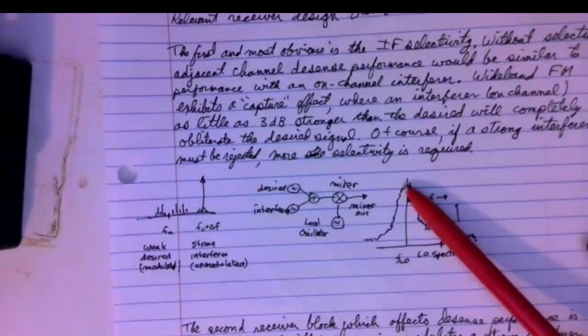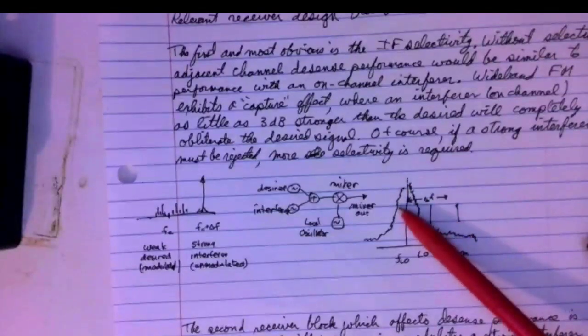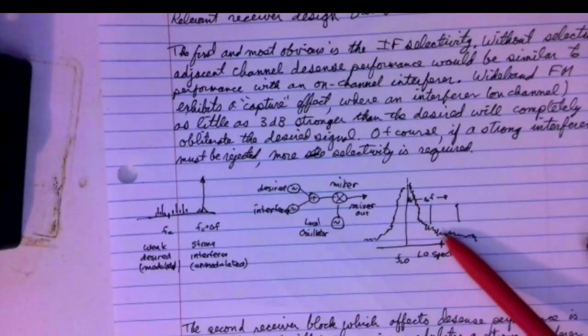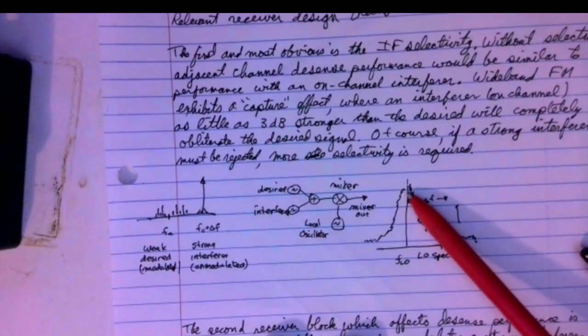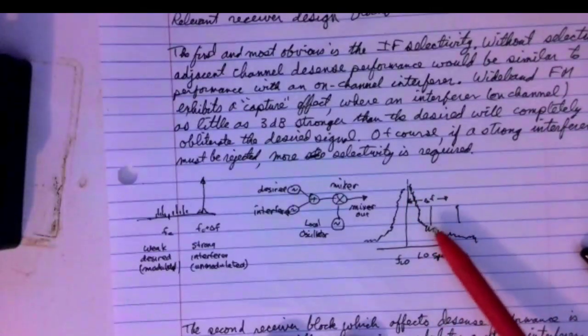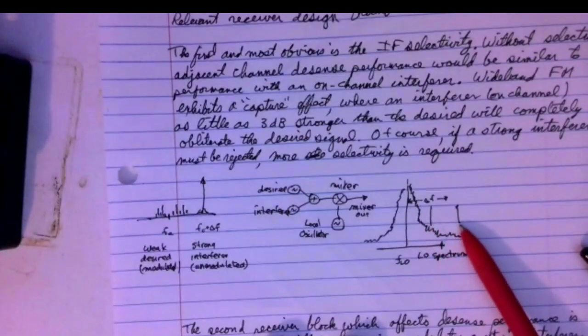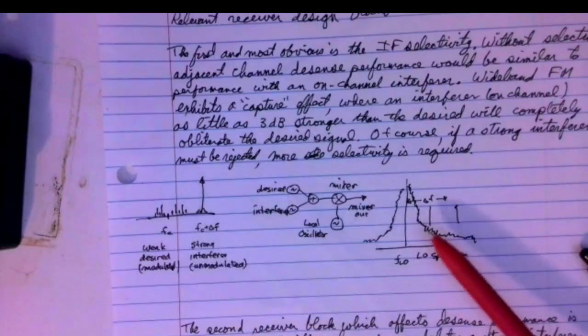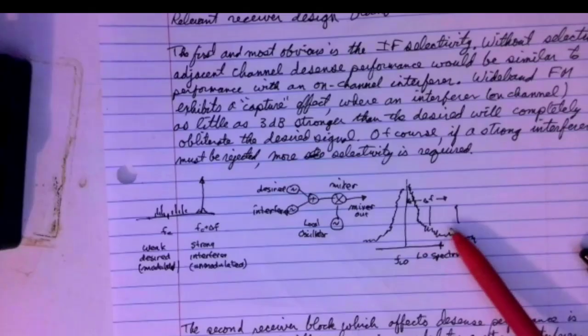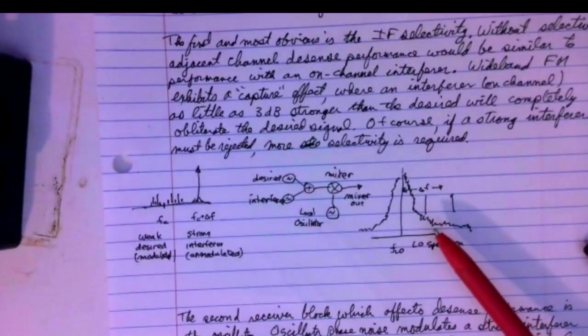This is what you want, the tone, a spike, but it's got a little Christmas tree around it of phase noise. And so the close-in phase noise is this stuff here, and then the phase noise we care about is this stuff out at an offset, whatever this offset is. We care about the phase noise at that same offset from the center. Okay, and I'm trying to show you why in a minute here.